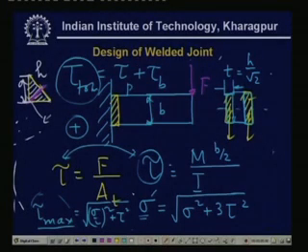So, now we have learned various ways of designing the joints for variable loading. There are at least two techniques for the welded joint, namely the usual Soderberg, Goodman or Gerber line criteria, but there is another technique using the allowable fatigue stress. So, the maximum design stress will be less than this allowable fatigue stress. This is how normally these welded joints are designed.